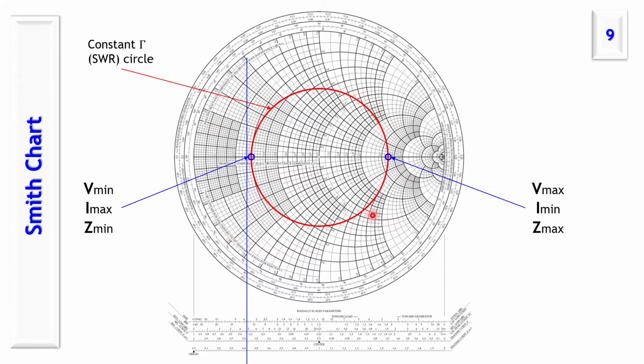So in this motion, the input impedance can be maximum, or it can be minimum. It's changing as you move along the line. You can prove this from the expressions. So as I said, we can start at any point on the circle for input impedance, and if we rotate or move by 0.5 lambda, we'll come back to the same point.